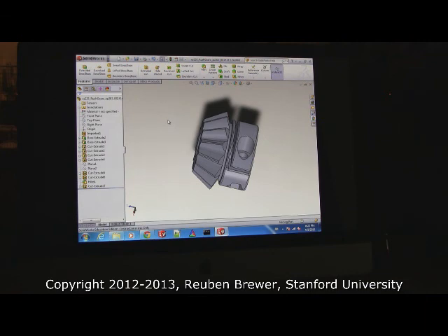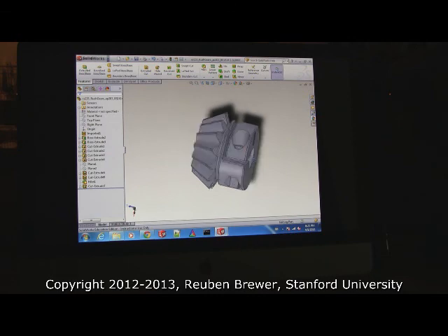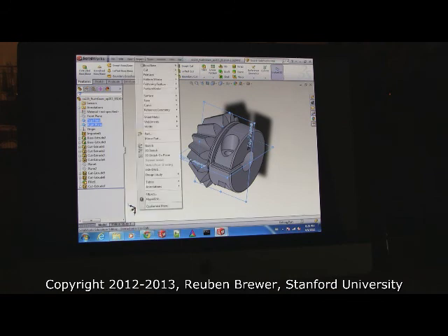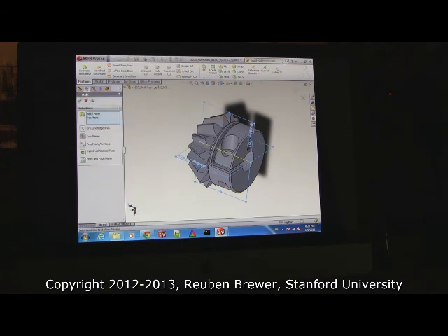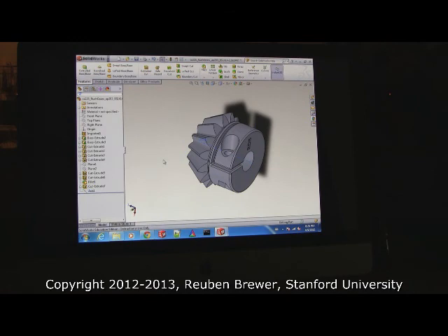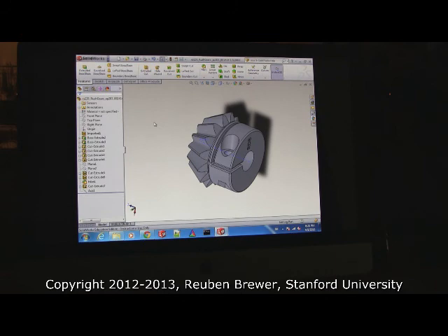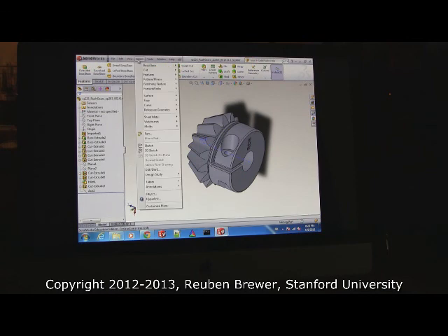Okay, now I'm going to explain why. So go ahead and look at my screen. Imagine we put a, actually I'll show you this real quick. Take the right plane and the top plane, insert, reference geometry, axis, green check mark. We have an axis. And I'm going to leave this visible. So go ahead and do that. That's the last step. Right plane, top plane with control. Insert, reference geometry, axis. And you'll see the axis pop up. Hit the green check mark.